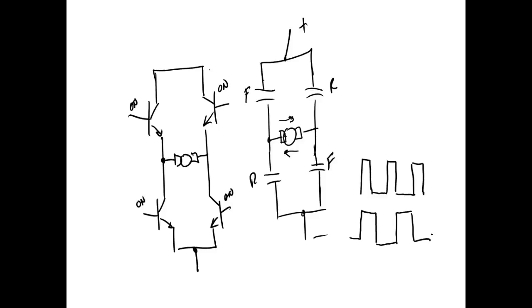So what we're not doing is changing the frequency. And a lot of times the frequency would be above the human ear. Sometimes it's not, and you hear these things sing at you, because you're hearing the windings on the motor pulsing. But what we do is, they call it a duty cycle. The duty cycle is the percent of the period. So the period is the time for one cycle, right? Everybody understand that? The duty cycle would be the percent of the period. So you can calculate the average voltage. You just take the maximum voltage and multiply it by the duty cycle, and that gives you the equivalent voltage.